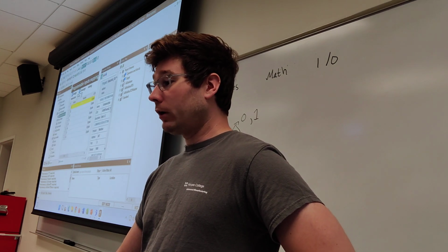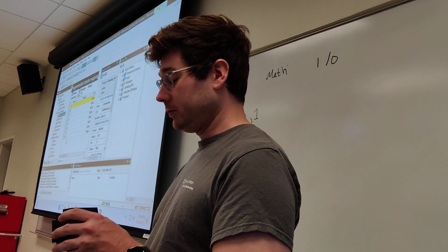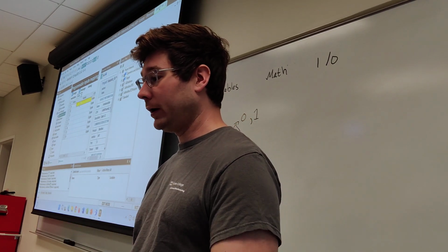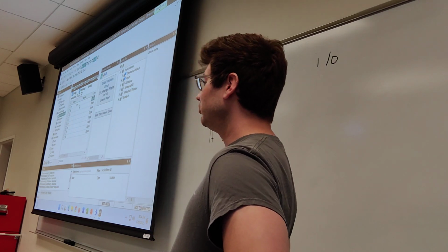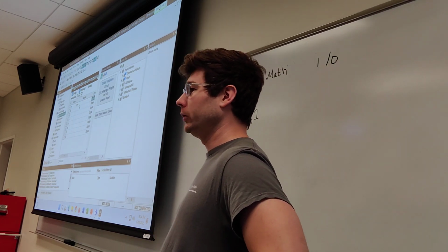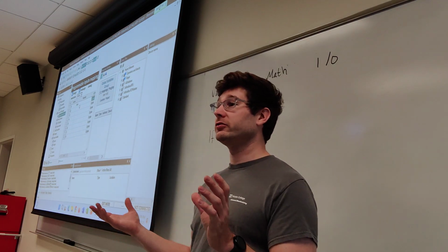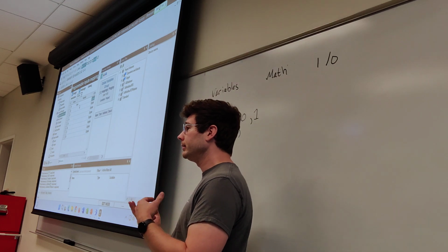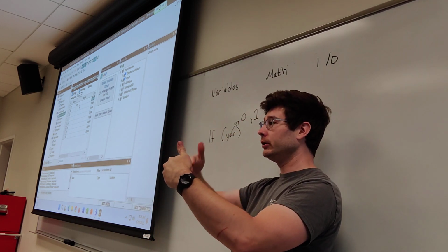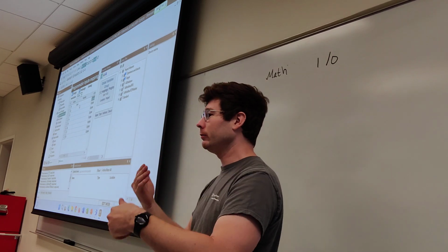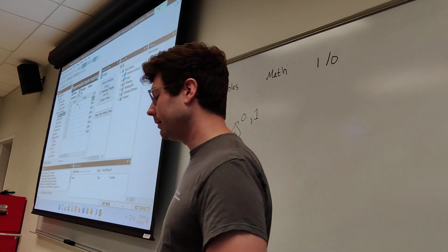All right, so far we've talked about programmable inputs, right? Our I1 through I8, which is the top of the device, how we can assign variables by typing in unique names, and wherever we use that name, we'll talk to that input, right? So for example, if I have an infrared sensor, it's measuring the amount of infrared light that's hitting it. Maybe there's a laser going into it, and when we block the laser, we don't see that light anymore, and we're doing something with that input. We're checking to see if it pulses or if it's high or low, whatever.